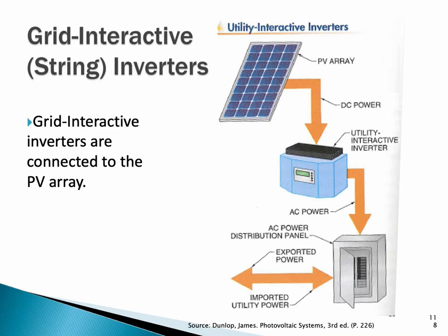Grid interactive inverters, they're going to look for the AC signal from the utility and match that in its production. So say the grid is running at 240 volts, the inverter will put out around 241 or 242 volts to push back against the utility. So it's just a little bit more voltage, a volt or two, that allows it to push back and feed the loads inside the breaker panel. Any excess would push back against the utility through the meter.